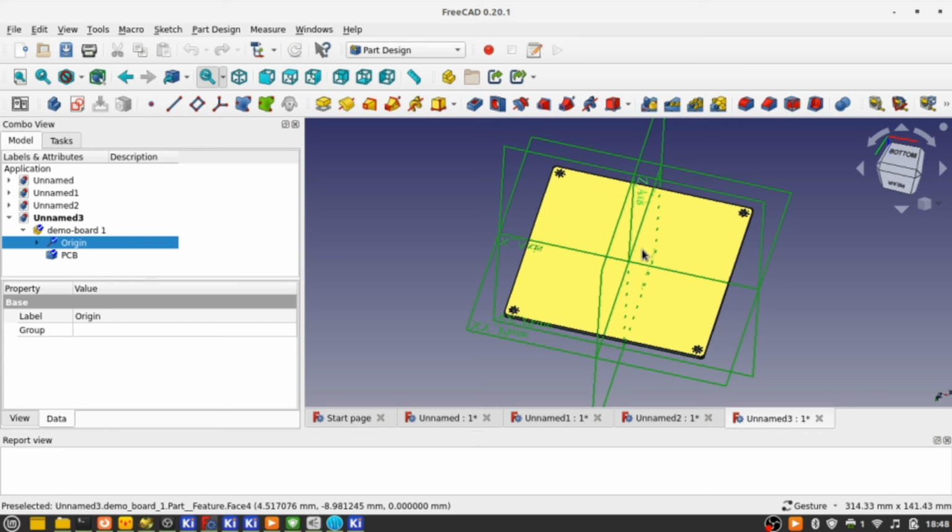Obviously, use semantic versioning. Don't stomp on all of your previous designs if they're working and already set up. If you make a change to the board, roll the semantic versioning. If it's a little change, change the revision. If it's a larger sort of mechanical change the minor version. And if it's a major shift, maybe you're moving to a completely different kind of enclosure, but it still has genealogy connections, change the major revision. Yeah, that's all I wanted to share.